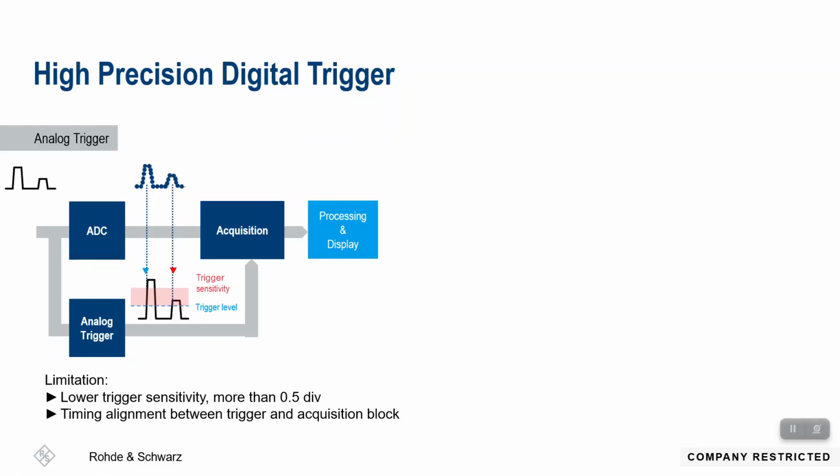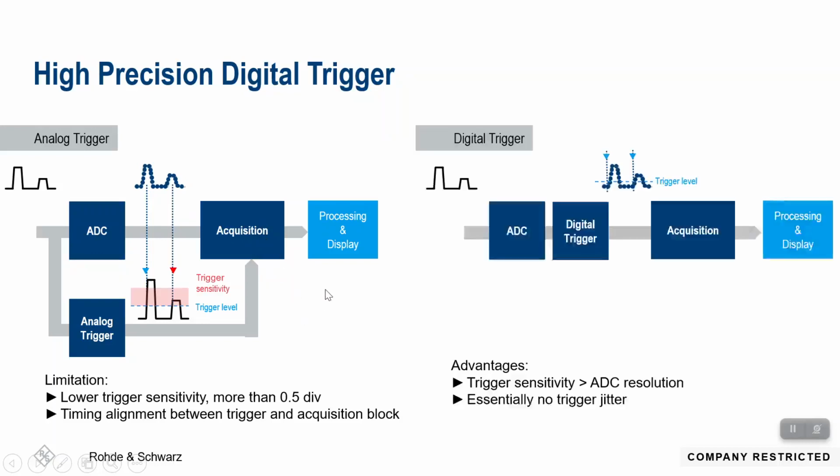It's in the data sheet for oscilloscopes, but that has to be met for a trigger event to occur. Meanwhile, the ADC samples the acquisition and processes that, etc. But if a trigger event doesn't happen, then that acquisition is thrown out.